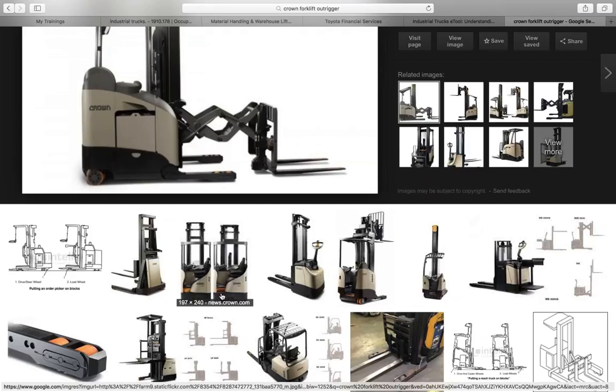Of course, we want to travel the smoothest route possible, and try to avoid as many rough surfaces as possible, so that we can better control our load and minimize the bounce. Traveling with long loads can present certain hazards as well, so we want to be cautious. We might have to watch the distance, add more distance and give a little more space, because we may have more bounce at that point of travel. We may have less load balance as well. So make certain considerations for it.